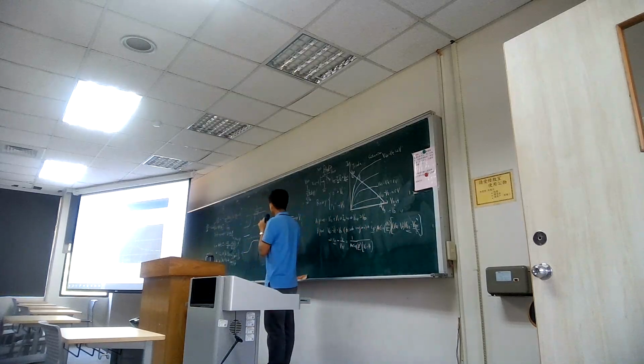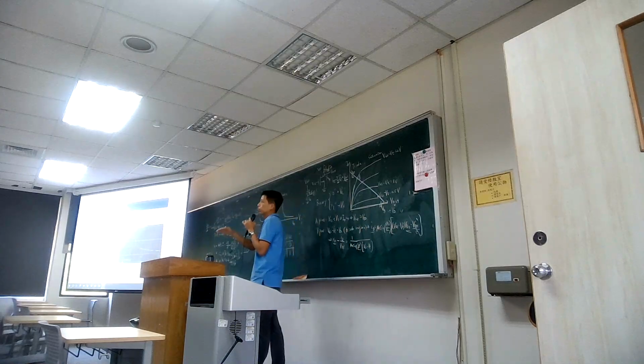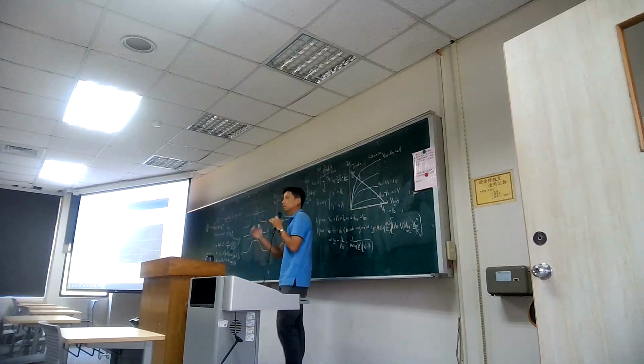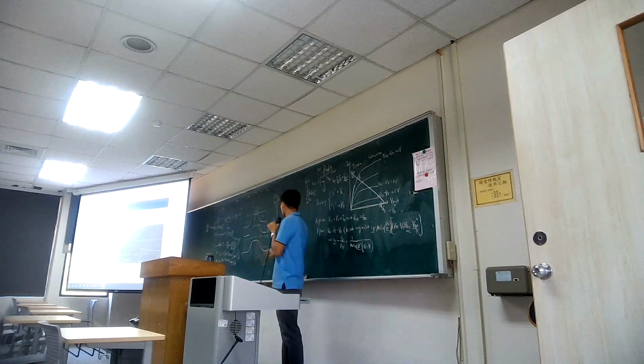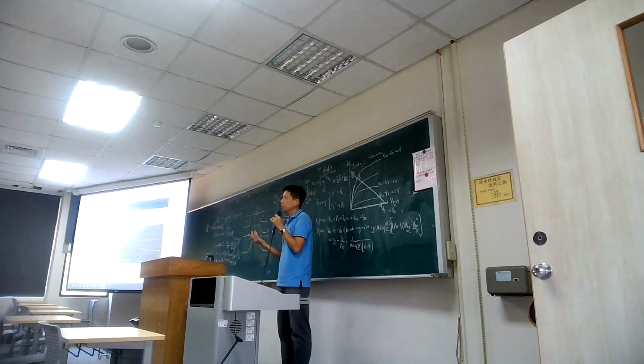In digital circuit design, you also need to know the minimum margin you are allowed. For instance, you may still have a certain low-level voltage, like 0.3 or 0.1. If the VDD is 10 volts, that's definitely fine, because it is typically divided at 5 volts. If the voltage is higher than 5, we call it 1. If the voltage is less than 5, we call it 0. So if your output voltage is 1 volt, it is pretty safe to say it's a low voltage.